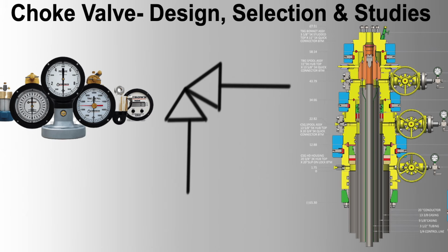4. Electric choke valves. Example: used in automated production facilities where integration with digital control systems is required. Advantages: easily integrated with digital control systems, e.g. SCADA, DCS, for automated control. Precision, provides accurate control over valve position. Remote operation, facilitates remote operation and monitoring.